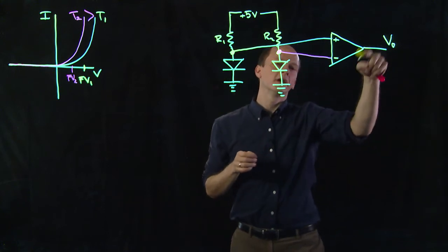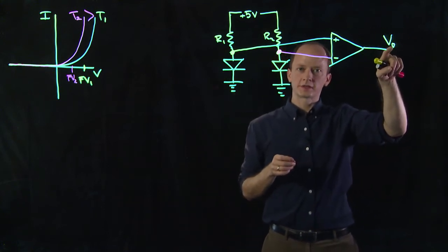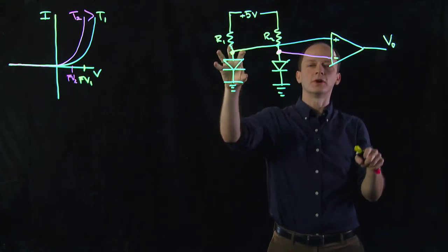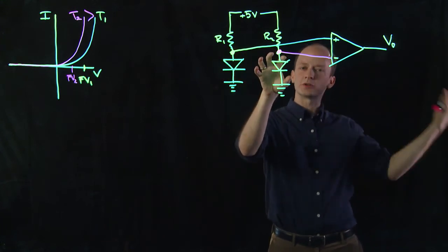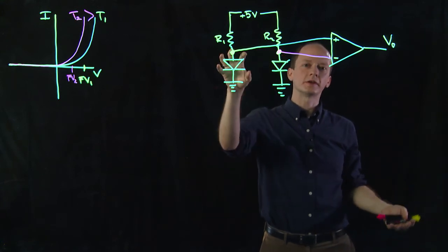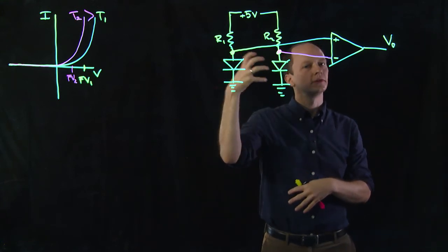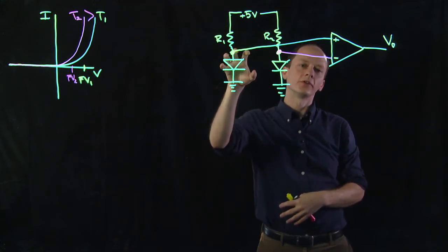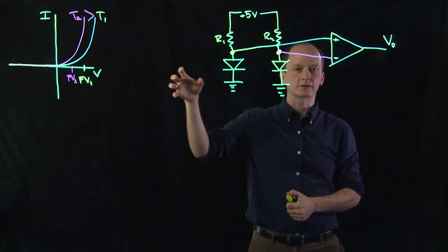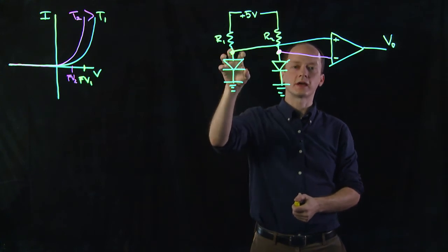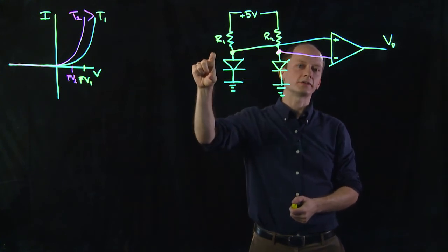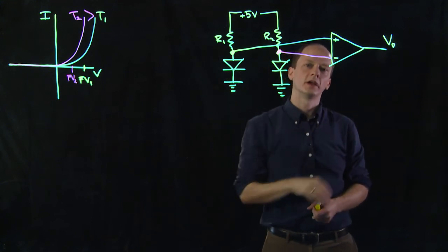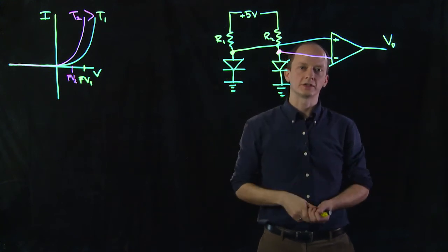and stay that way as long as there's a temperature difference between these two, right? So we can use the output V out here to say which one of these diodes is actually hotter than the other. We can use one as a reference to say this is the temperature of the room, and then we can use the other as the sensor, right? So in particular, for your design challenge, you can use this as the sensor for the grain of wheat toaster that you made last week. And you can use this diode to be sensitive to that toaster as it heats up, monitor that temperature and then decide to do something afterwards, which is what you're going to do for your design challenge.